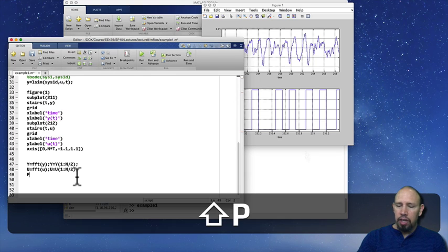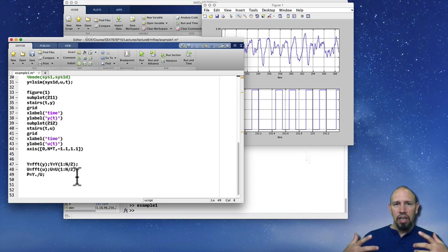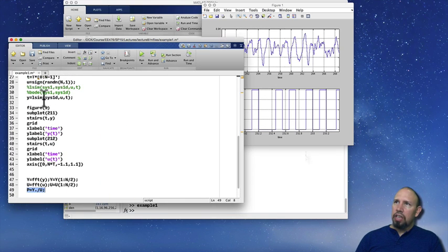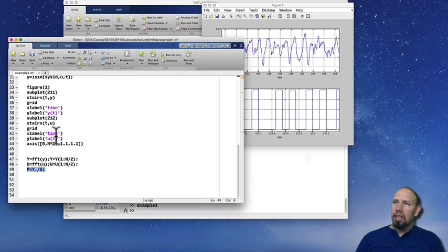So I'm going to define p to be y dot divide u. Remember, because these are data vectors in the frequency domain, I need to do a dot divide in order to do the element by element division. So this is an estimate of the transfer function of our system. Remember, the system was actually sys1d. And so this is an estimate of our transfer function.